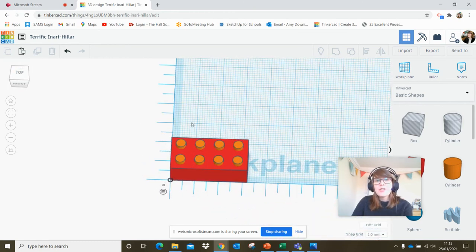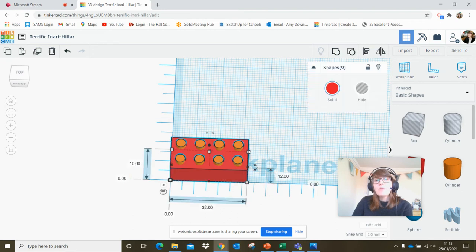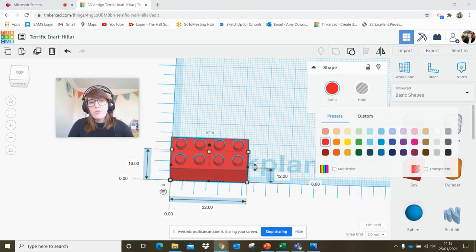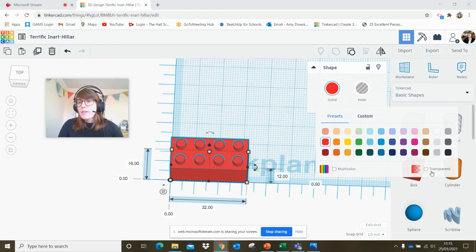We're nearly finished. Highlight the entire shape. And the last thing we need to do is then group all of this together using the control button at the top here, group. And I'm just going to show you what you can do in terms of adding some colour to this to check that it is a hollow shape. So when you send me a print screen of this, I can see. Just go to Solid, move me out of the way a little bit, there you go. And I'm going to click the transparent tool here, and I can select my colour, and I can also set the transparency.